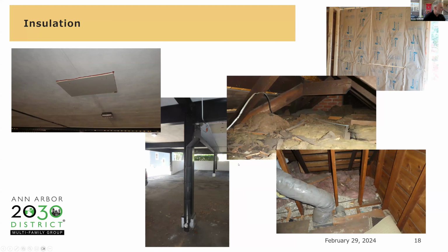And then up in your attics, remove all the old insulation. Insulation companies will come and just vacuum it out. That way you can see really well what you're up against and what you need to do to air seal the ceiling plane before you insulate, and then re-insulate with as much insulation as you can. Once you have an insulation technician up there installing insulation, it's relatively inexpensive to go from say R40 to R60. They're already there and doing the work.